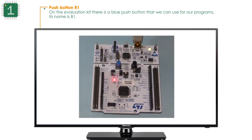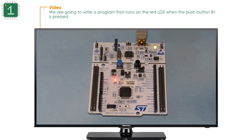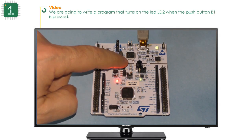On the evaluation kit there is a blue push button that we can use for our programs. Its name is B1. We are going to write a program that turns on the LED LD2 when the push button B1 is pressed.